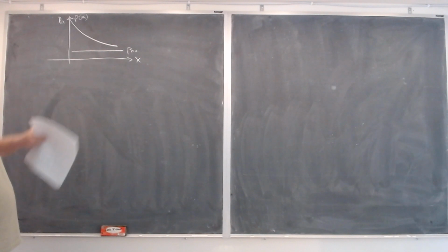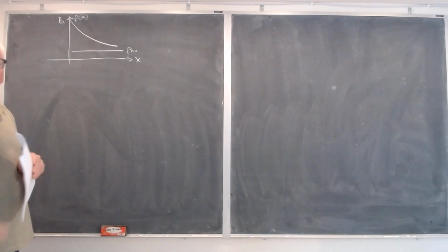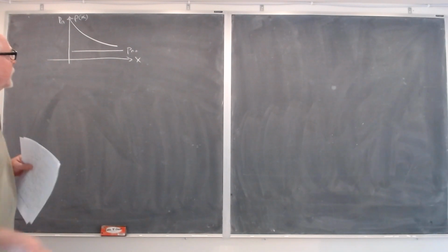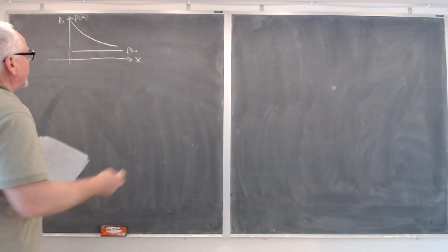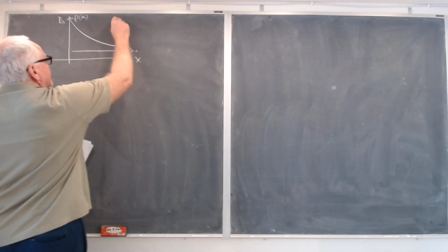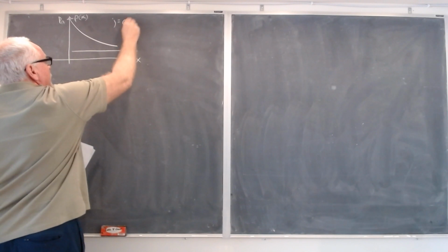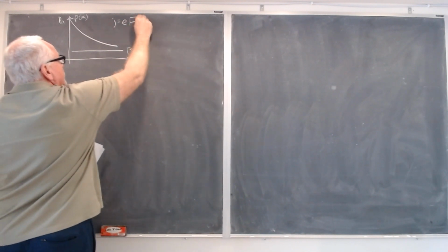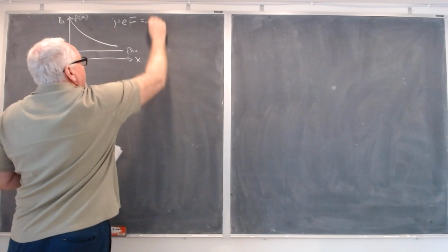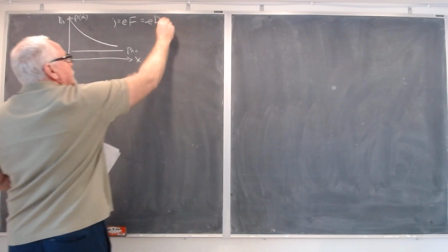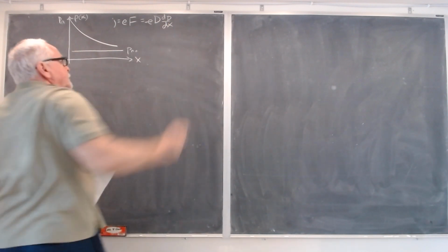the reason why I'm doing that is because I want you to understand a simple way to come up with a diffusion current, so that you don't have to memorize the formula, because all you have to memorize is that J is e times the flux, so it's e, minus sign, times the diffusion coefficient times dP dx.